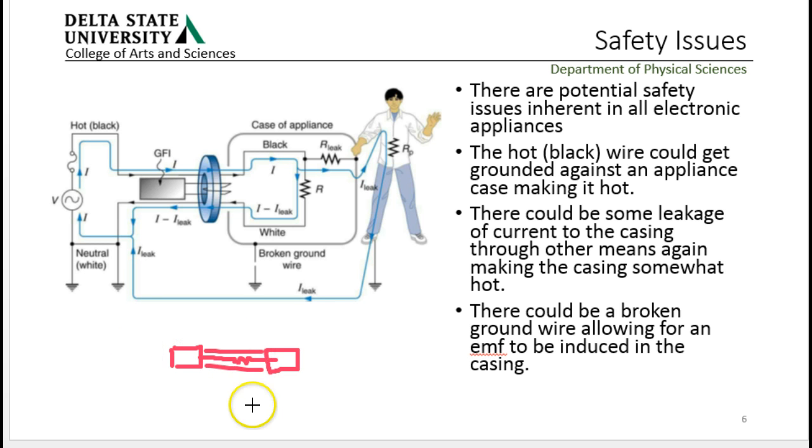Well, that wire is designed so that when you hit the current limit, which is typically 10 amps or 15 amps for most fuses, the wire actually burns out, right? And it breaks the circuit. You'll see them in your car. There'll be a little plastic package like this, with a metal tongue coming out like that, and then a little wire you can see here. They always make the wire that's the fuse part visible so that you know when it's burned out. And again, when you flow too much current, that element physically evaporates.